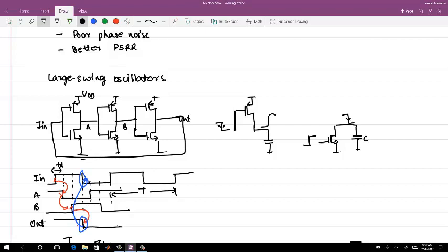So it goes the whole cycle of 0 to VDD. And for this delay you can work out the effective resistance of these MOS, and the delay of charging and discharging. You will size the inverter so that the charging and discharging delays are roughly the same.